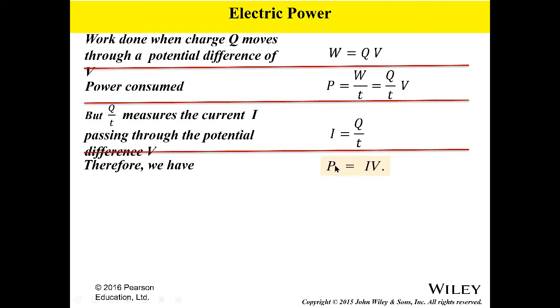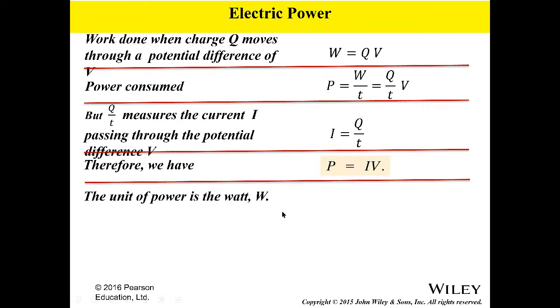They don't tell you what is the current that will flow, because it really depends on the voltage that you put in. And they don't tell you the resistance of this air conditioner, microwave oven, or refrigerator. They only tell you the power, and that this rating is for use in America, so the voltage is 120 volts. And the unit is watt.